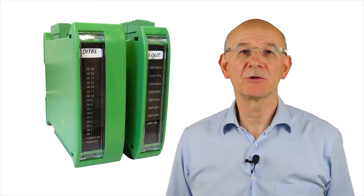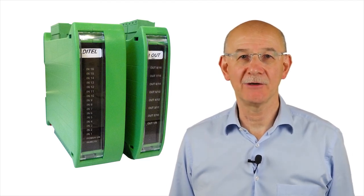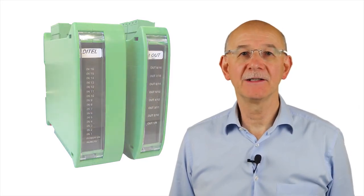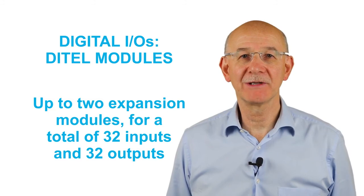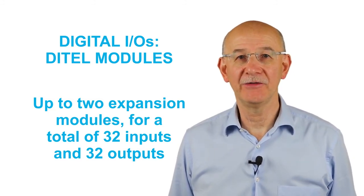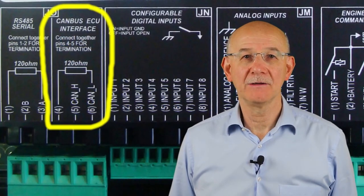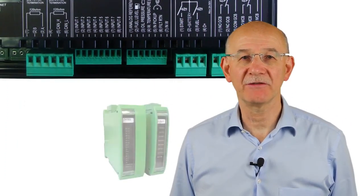It is possible to expand the number of available digital and analog inputs and outputs by means of external modules. Regarding the digital inputs and outputs, up to 2 expansion modules can be connected for a total of 32 inputs and, if included, 32 outputs. The expansion modules must be connected on the CAN bus ECU interface.